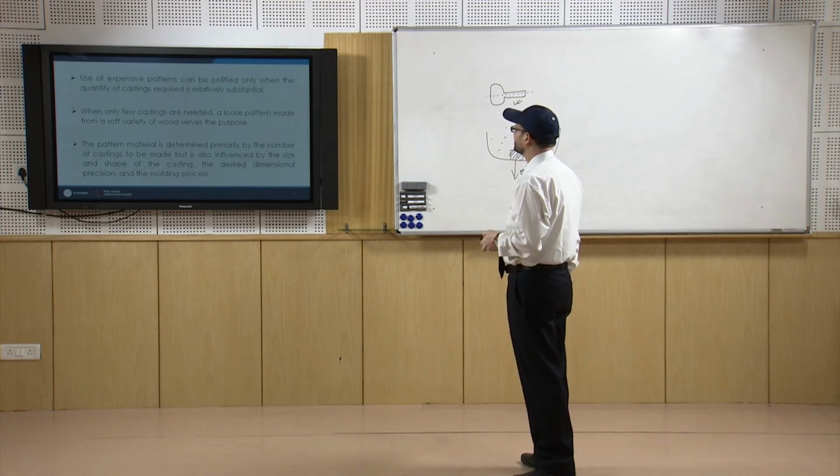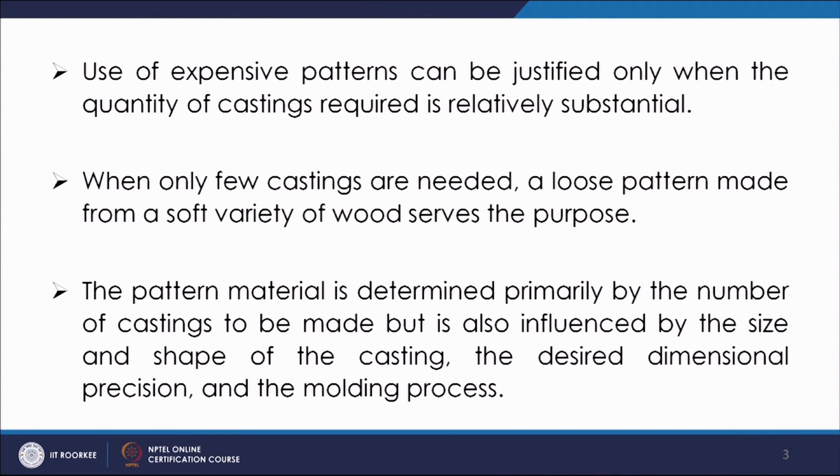Pattern material is determined primarily by number of castings to be made, but also influenced by size and shape of casting, desired dimensional precision and molding process.